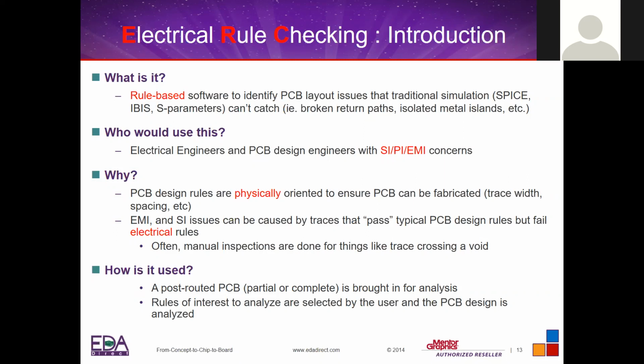So the target audience for this is not the expert SI engineers. This is for layout people. You just finish your layout. You think you're done. You should be able to run this DRC check before you say yes, it's done. That's one case. The other case is if you have many of these designs per year, 5 to 10, 20. I don't have time to run through all these simulations. Well, let's submit all these boards for checks to see if they pass or if they see any issues.